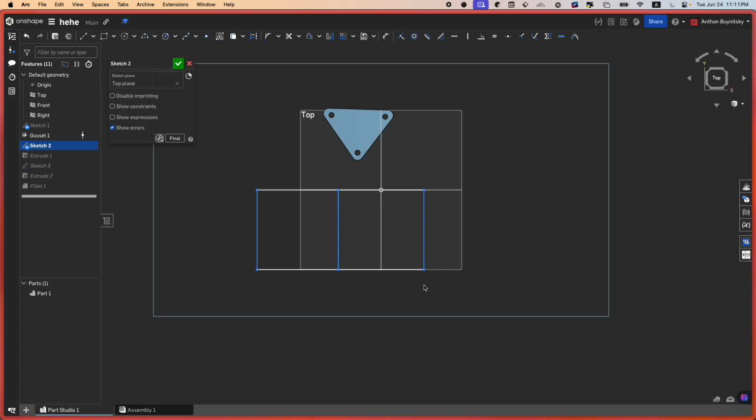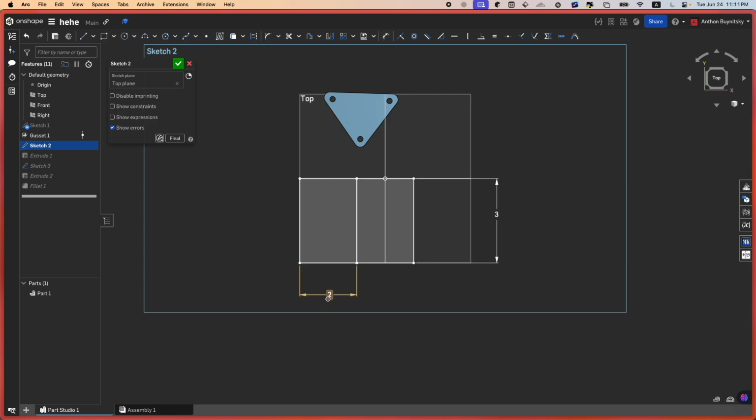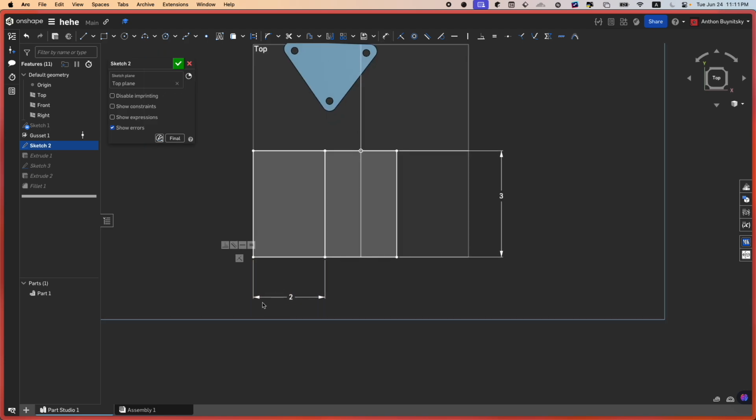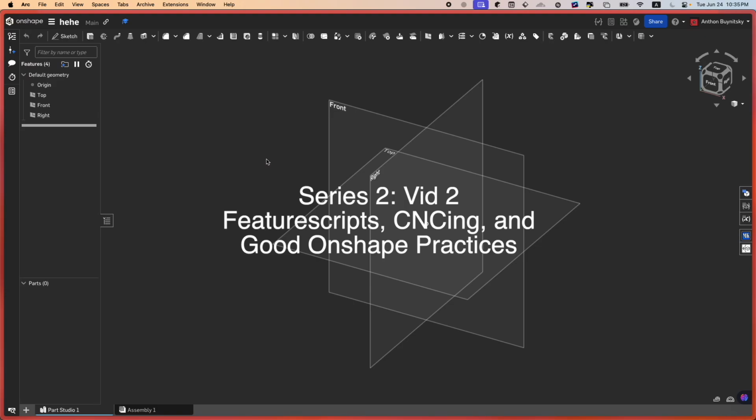what's a really easy way to check what is constrained and what is not constrained is quite literally just use your mouse. So press and hold on anything that's blue and try to move it. That is then you'll know what to coincident. And then now what I'll probably do is I'll make the widths of the two rectangles coincident, and then I will attach a dimension to them. So as you notice, I did not really have a goal for this part.